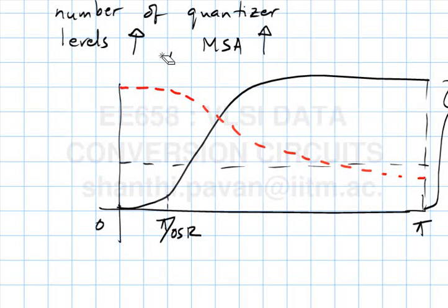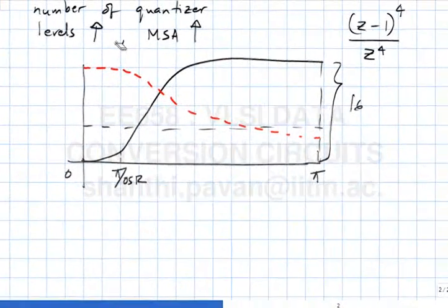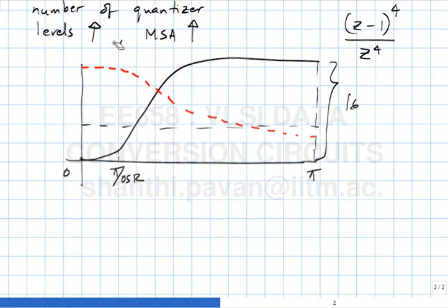Hopefully, we'll see that that's not entirely true, but clearly the out of band gain is reducing, which means that the variance of the noise at the input of the quantizer will reduce, which means that the stability of the modulator will be enhanced. In other words, overload now happens a lot less frequently, which means that the gain of the quantizer falling off also gets delayed, which means that you can put in larger input signals before the quantizer overloads and causes the whole modulator to become unstable.